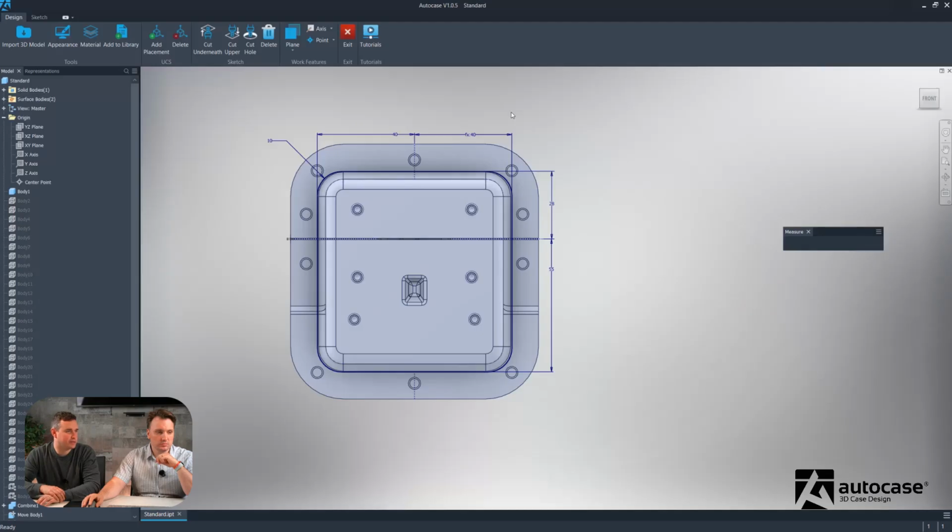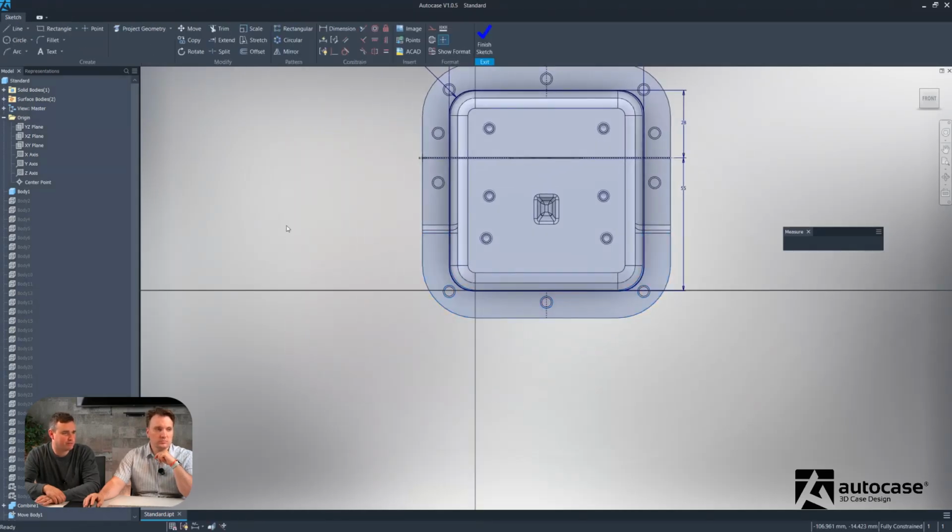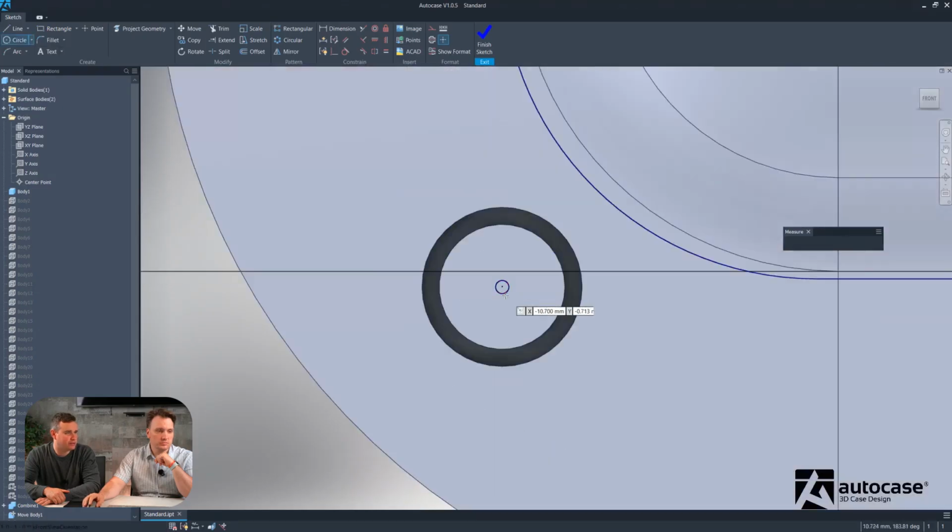So we'll put some 5 millimeter holes on there now. So we use the cut hole function. Again, we're creating a sketch, so we have to select the face that we want it to be registered to, essentially, and linked to. So always select the face of the piece of hardware that's going to be touching the outside of the case. Right, so draw some circles using the circle function.